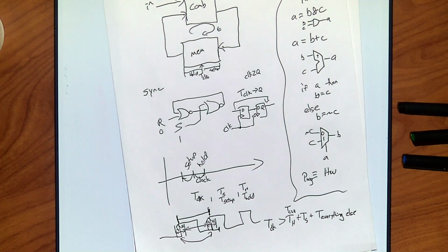More and more new logic families are just zeroing T hold and then just specifying clock to Q, and they do that max for you so that you're always just getting the real state value. Which is why I mentioned newer ones tend to ignore hold and make it zero. It's not that it's actually zero, they're forcing you to just get clock to Q and pick the safer number, whatever's bigger. Does that make sense?